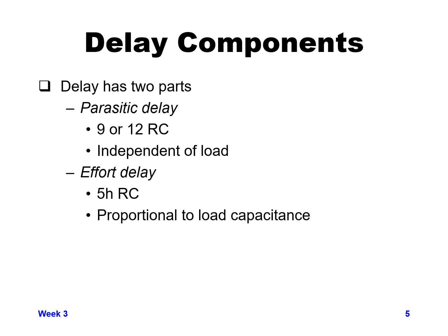Keep in mind that that's always true any time you have a gate connected to something. You have a parasitic, independent of load delay, and some additional delay based on how many things you're trying to drive and how much load you place on it outside of the gate.